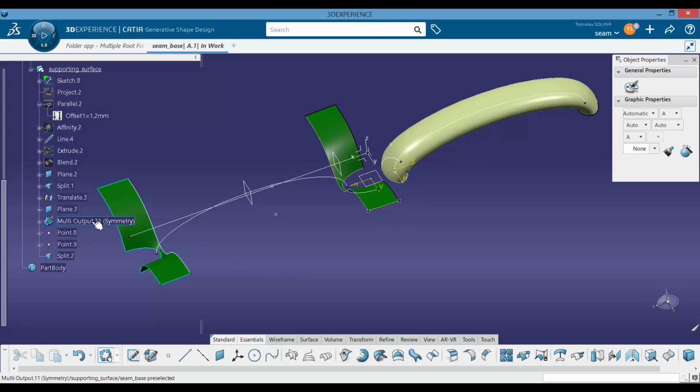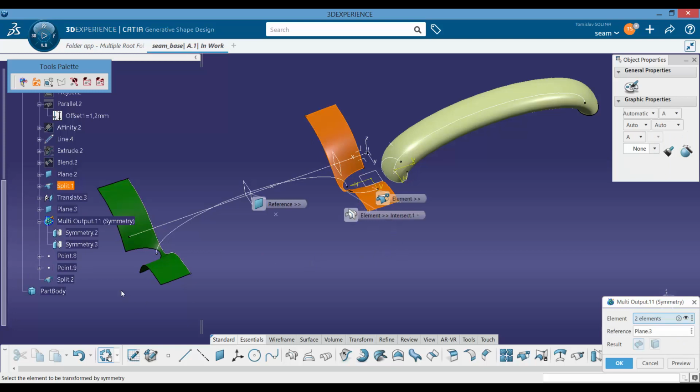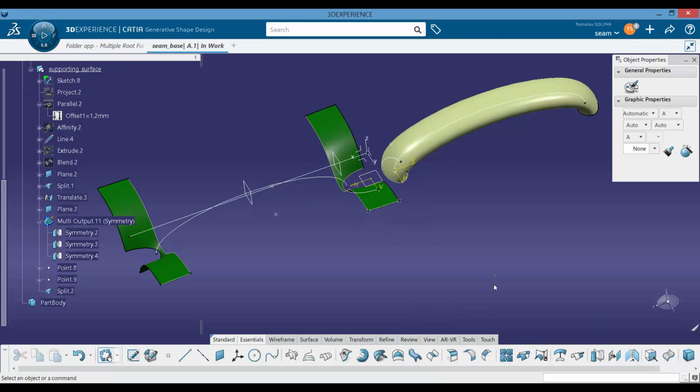So as we made a symmetry already, we can just attach this element to it. We'll select this symmetry, we'll open the list, and in this list we'll add an additional element. Okay. As those are ellipses, we will have turn in and out. So let's do this.